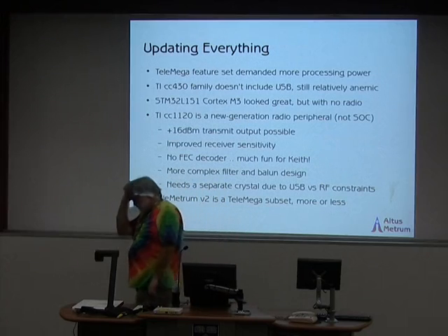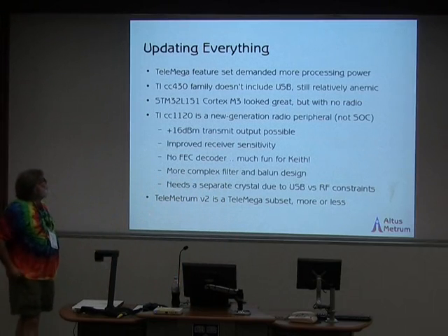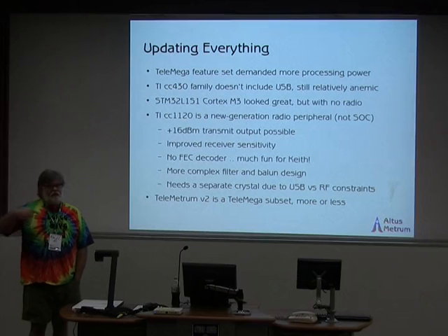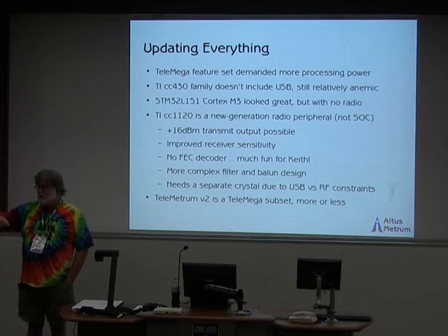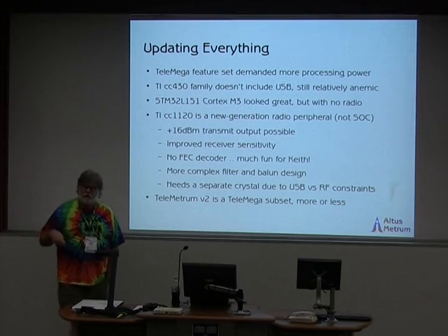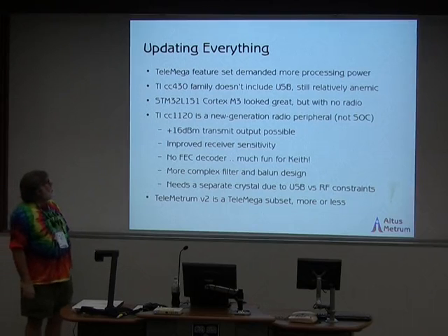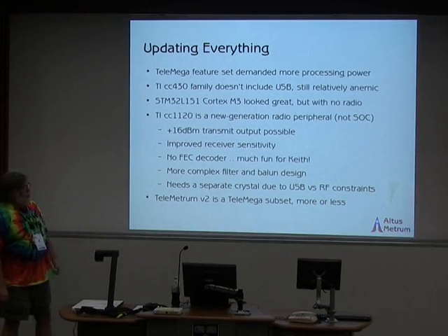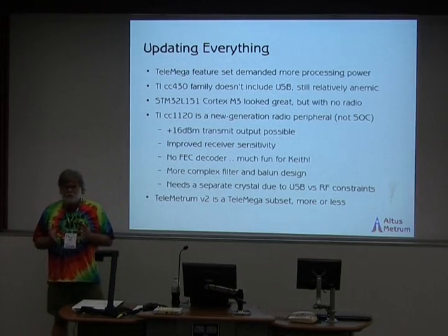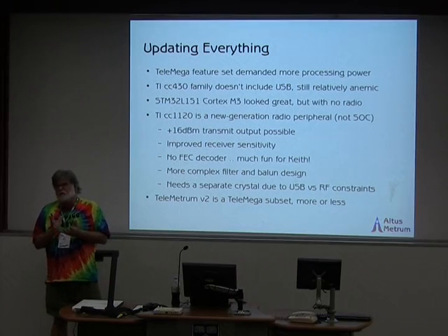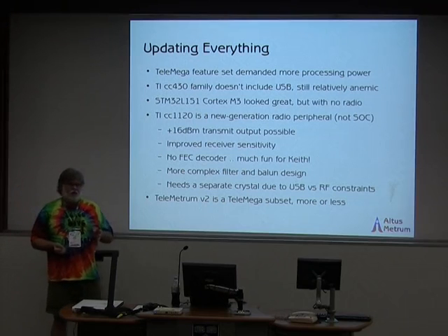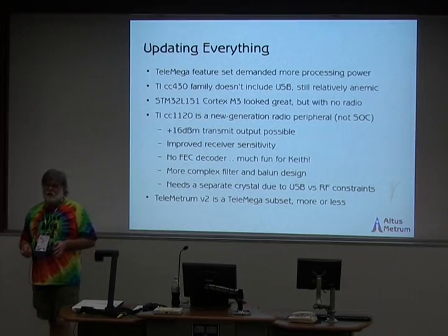But then stuff changed. I got this crazy idea that it would be nice to do a flight computer for supporting more complex flights. And in the rocketry world, that means instead of just a pyro event at apogee and another one coming down to put out the main parachute, wouldn't it be cool to be able to air start additional motors or support multiple staging, and so forth? And another thing that was happening is that people were starting to recognize that if you're flying complex flights, being able to not fire extra motors or do the second stage ignition if something had gone wrong previously was a good idea. What do I mean?